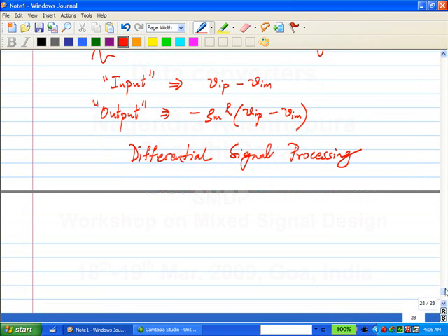All right. So, when we were talking about flash converters, we were saying we will compare Vin with V1 and so on, right? So now, if you go into fully differential circuits, what do you think we should do? This input difference is not any single voltage, it is the difference between one going up and one going down. So this is represented as VCM plus Vi and VCM minus Vi. So whenever you have two voltages, you can always express them as their average plus an increment and their average minus the same increment. Correct?